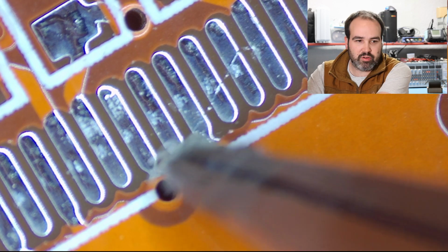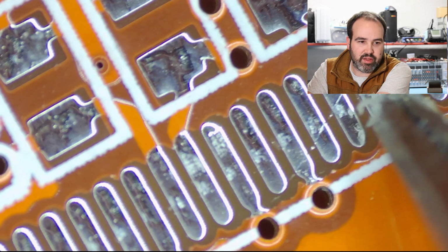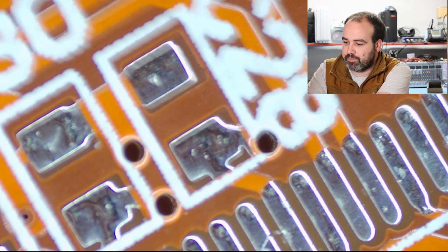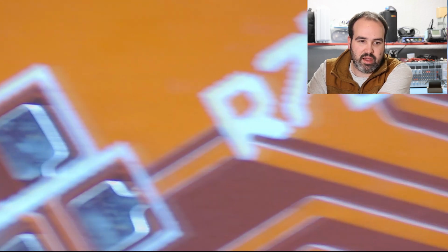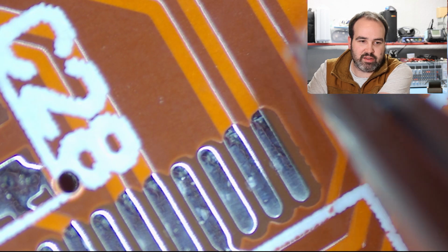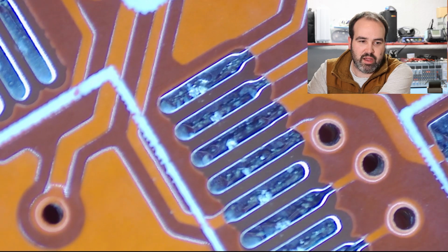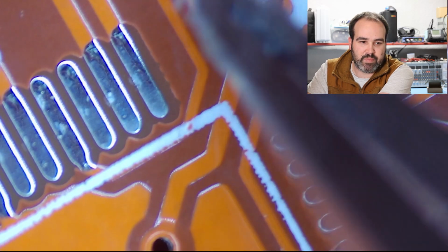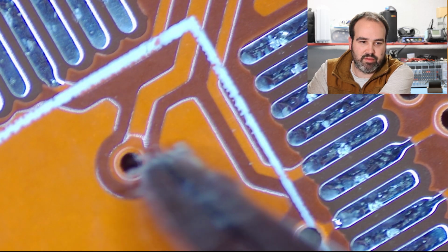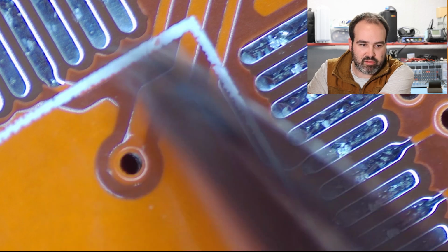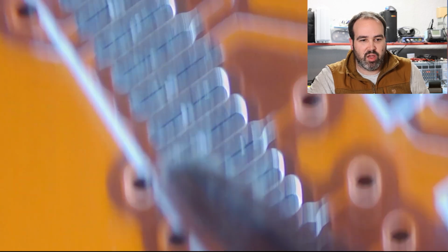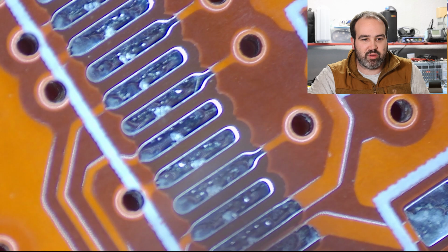These parts here we call the pads, right? So these are pads of my component. The component gets soldered onto these pads. So each of these is a pad. We have the traces, which are the copper that's actually carrying signals and power and things like that. Our via, which we've already brought up, connects between this top side and the bottom side. And the via itself is a combination of this outer pad, the drill that goes through the pad to the other side, and the fact that it's all plated together. So when we spec a design, we'll have some different things that we need to tell the manufacturer about what we want the design parameters to be, the size of that hole, stuff like that.